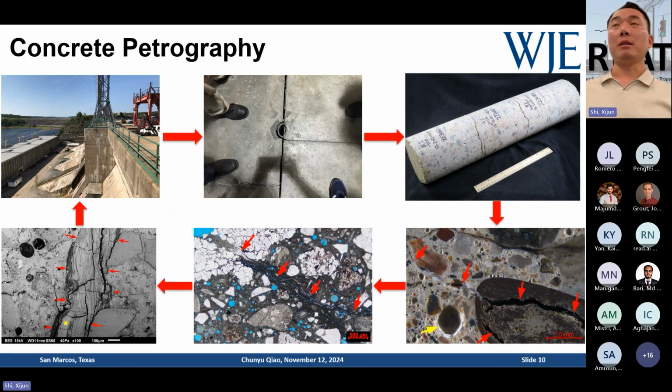You see this dam has a lot of cracks, deterioration, some spalling, some white efflorescence, or whatever you call it, exudate oozing out from the structure. So it is a critical condition. It is critical infrastructure for the local community. The engineers or the government or the agency want to know how safe the structure is and how bad this deterioration has progressed. So the owners normally will call some engineering teams to do an on-site inspection. A lot of times, I can tell you this is an ASR case.